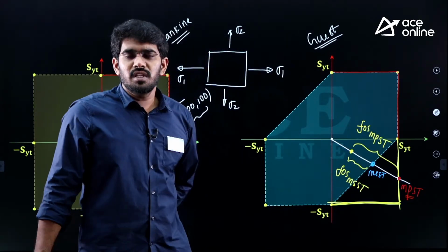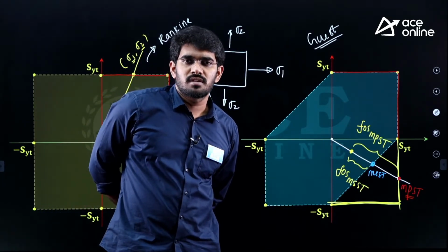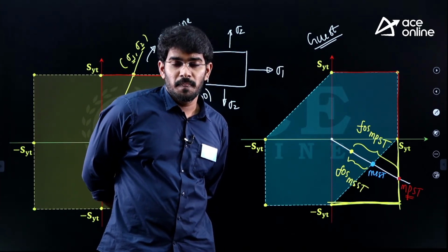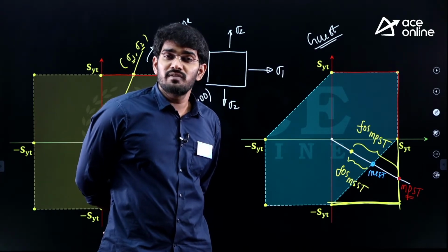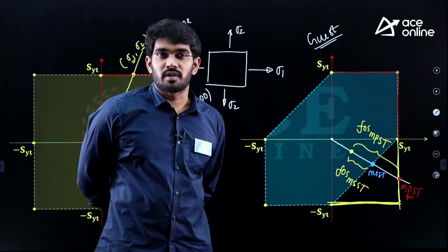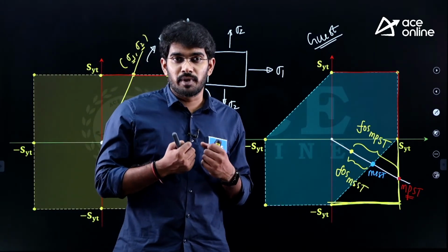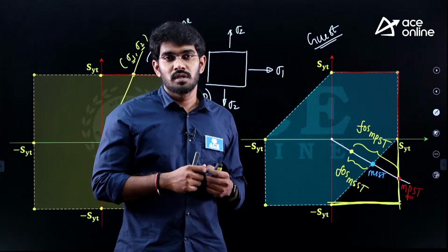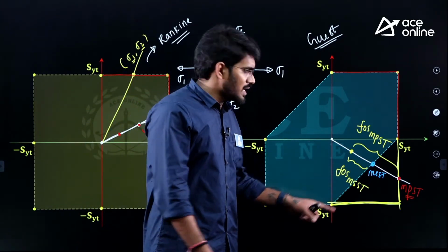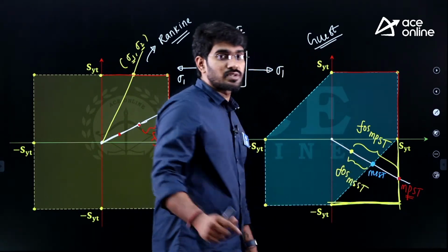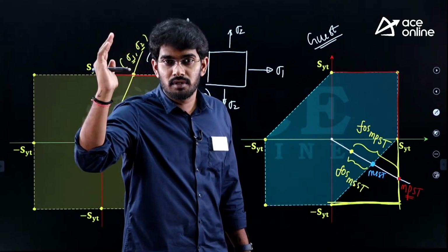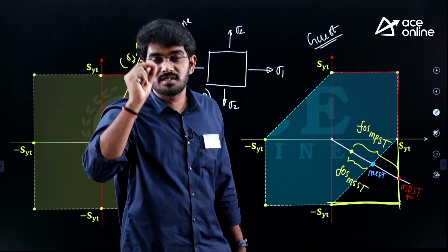Now, can you please say which safety is larger? Whose prediction is giving more factor of safety? See here, when we are considering predictions, we need to see the safe prediction. We want the safe prediction. Remember this always: for safe prediction, as this is considering lesser failure stress, lesser stresses are more safer. More stresses are less safer.